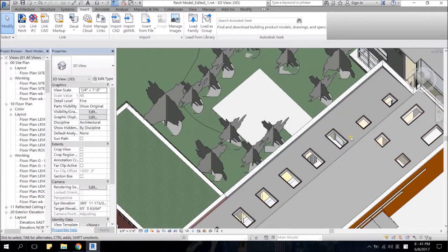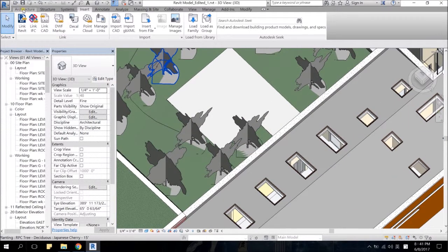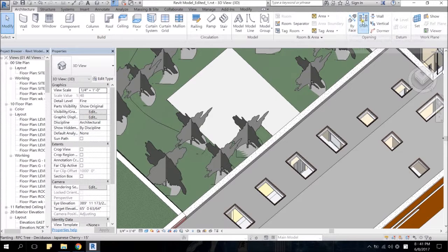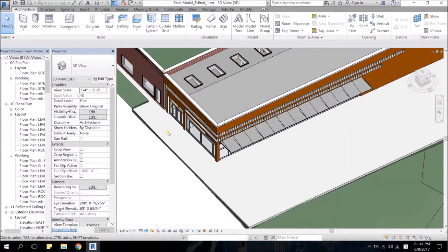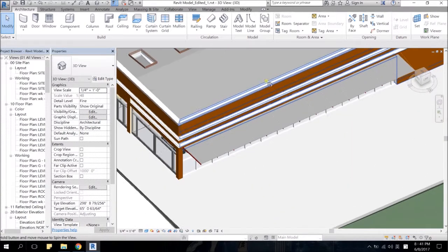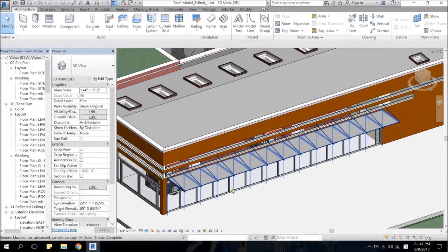And we have to further use the Shape tool in the Architecture tab in order to puncture the hole to bring in the daylight. I have further added exterior sun shading devices in order to block the sunlight for the spaces nearby the huge curtain wall.